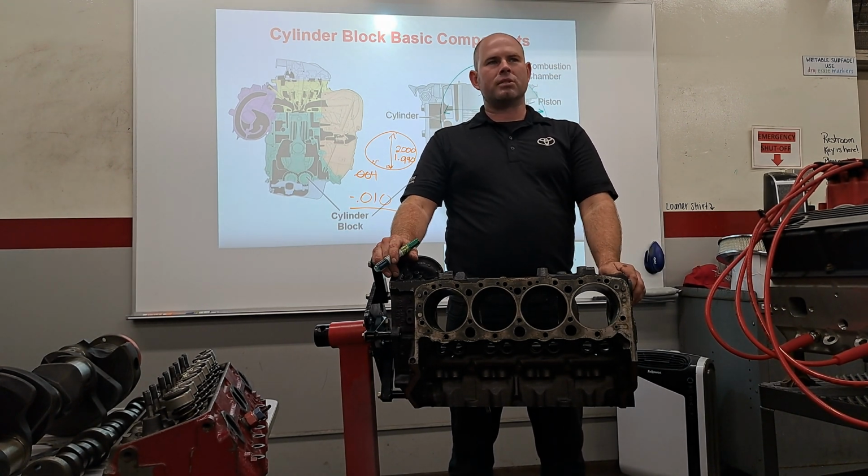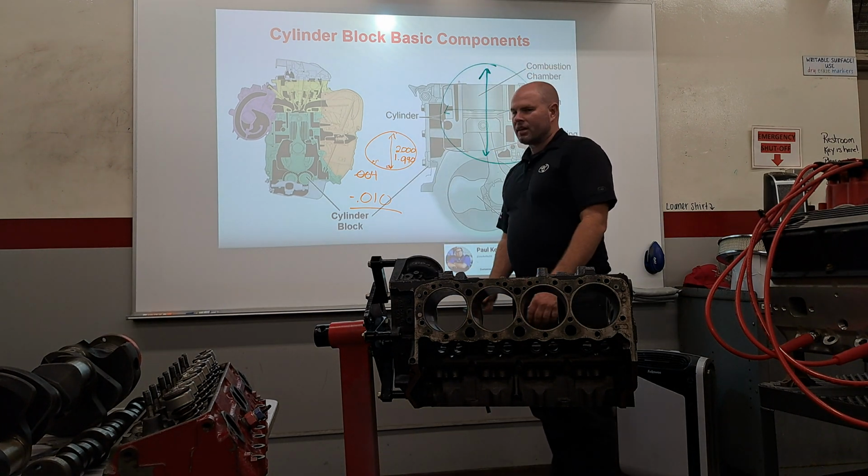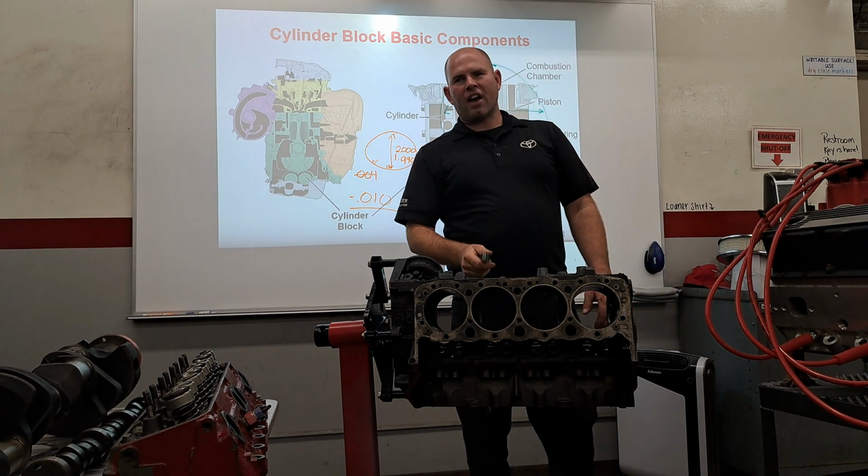So that cylinder could be out of round. If that cylinder is out of round, it's not going to have great compression. It's probably going to have oil consumption and stuff.